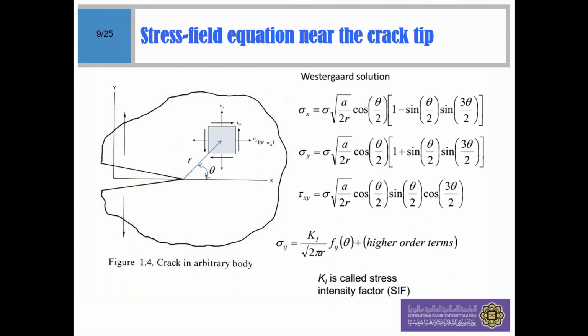The crack tip means at the edge of the crack. So, if I have a situation like this is my structure or my plane, I have a crack where this is my tension load, for example, acting on this surface. So I have an opening mode 1 crack.